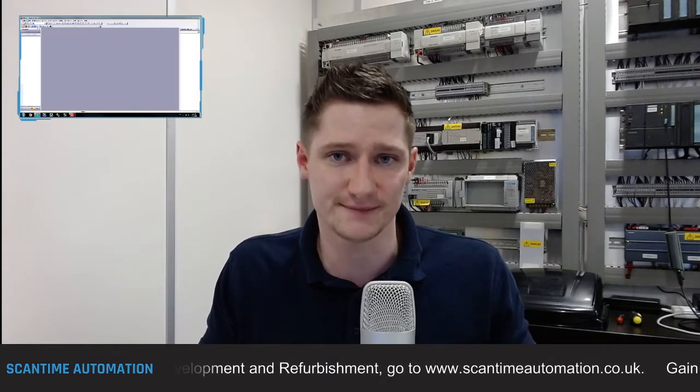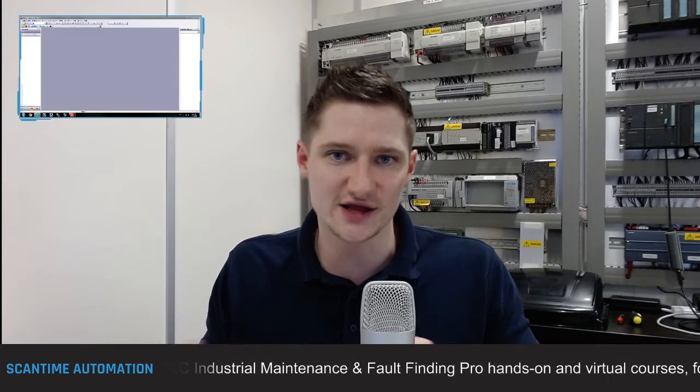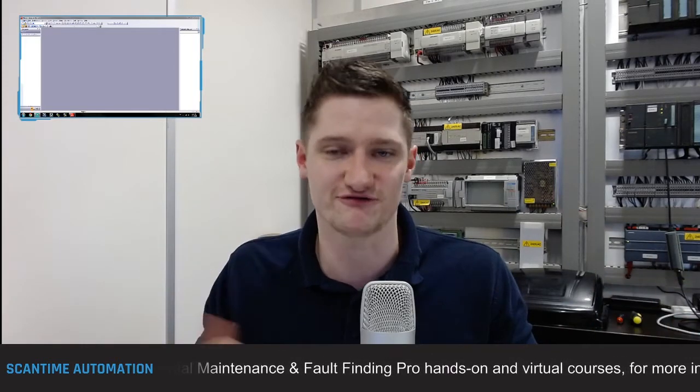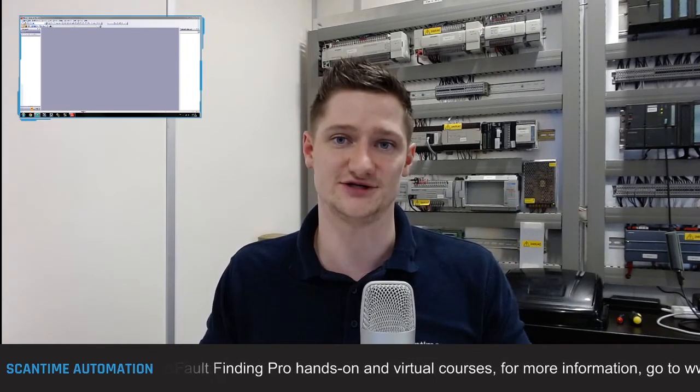Function blocks are blocks of code that can be used as many times as we want inside of the program, and we can address different forms of inputs and outputs to the PLC. So if you think about a timer or a counter inside of TIA portal, that there is a function block. Siemens has created that block using code inside of the PLC, placed it inside of the function block, and then they allow us to use it as many times as we want to create a timer operation. We can then tweak things here and there with different forms of inputs, different forms of outputs, but the fundamentals of the program remain the same inside of the PLC function block.